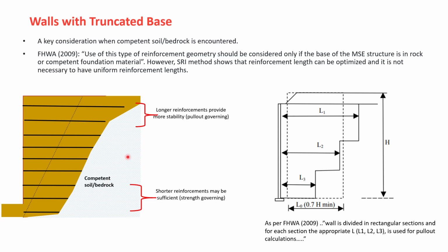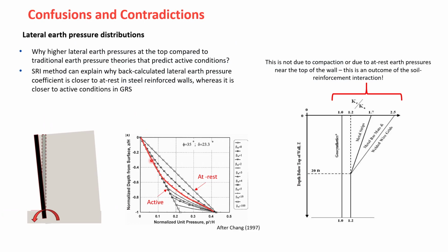But it's a bigger problem if you have a competent soil or bedrock. Do we want to excavate that whole thing out and put in uniform reinforcement length just for the sake of satisfying the database requirement, right? So those are the issues, and this is another interesting one.